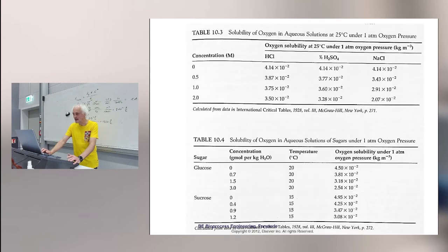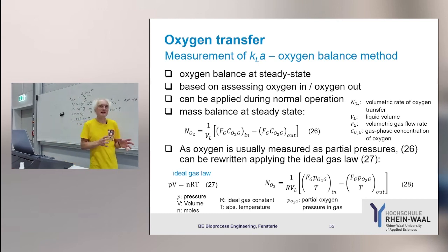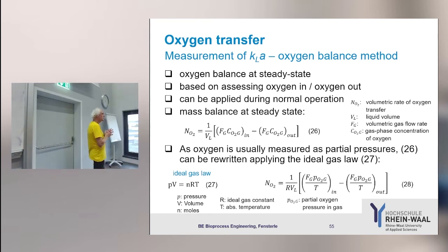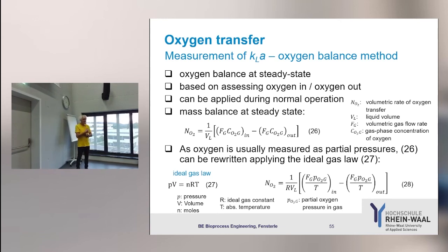So this I want to switch. Now we come to the way to measure oxygen transfer, and we can do two things. You have measured oxygen transfer rates using the dynamic method. So you have sparged in nitrogen and then measured the kinetics of oxygen getting in, and with this you have calculated the KLA value. Of course you can deduce that. Today we have no time to deduce it, but we have enough time that you can start with the homework.